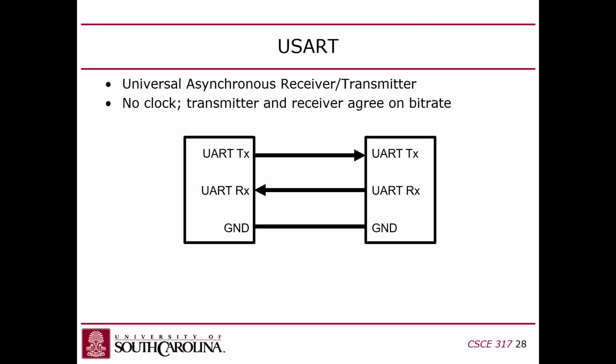So that way you don't have to worry about arbitration. You can have multiple readers, so you can do like a broadcast setup, if you just connect the same TX pin to several RX pins. It will work. Now you can cause signal integrity problems if you put too much impedance. But if you want full duplex...